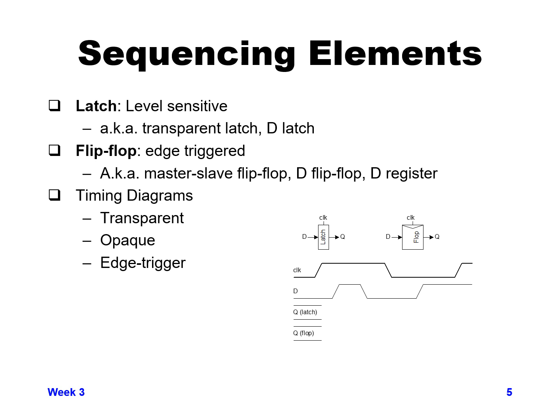So looking at the timing diagram for these two types of designs, the latch design is either transparent when clock is high or opaque when clock is low, and doesn't have a concept of edge triggering, whereas the flip-flop is edge triggered. It captures a value only when clock goes from low to high, and otherwise it's always opaque and it's never completely transparent.